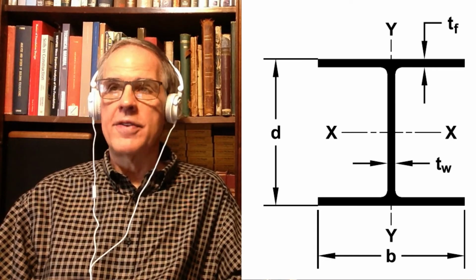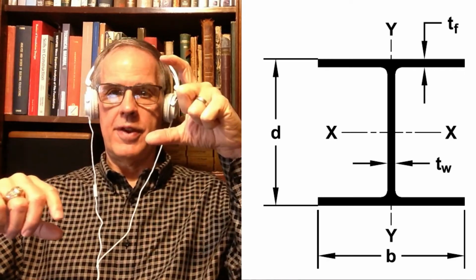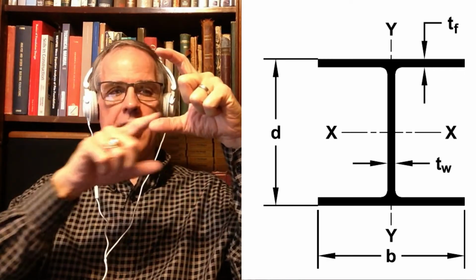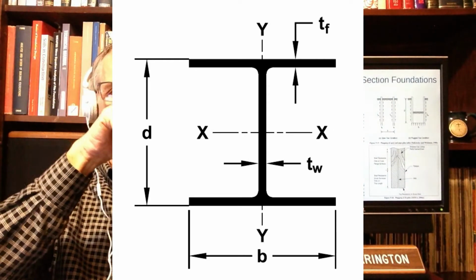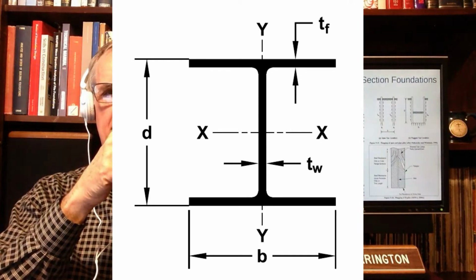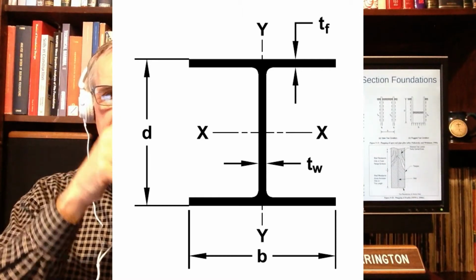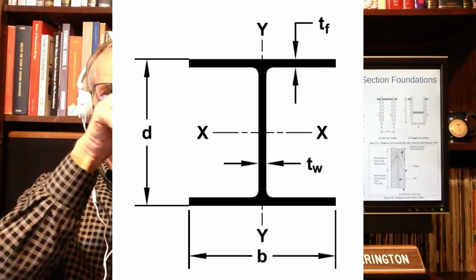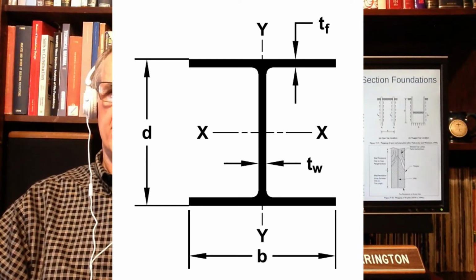If you get H-beam plugging, then basically what's happening is that between the tips of the flanges, in other words, if this is half the H-beam, this is the other half, and this is the plug inside, it shears along between the two tips, as you see a little bit in that photo. And all this area here is no longer really available to you.